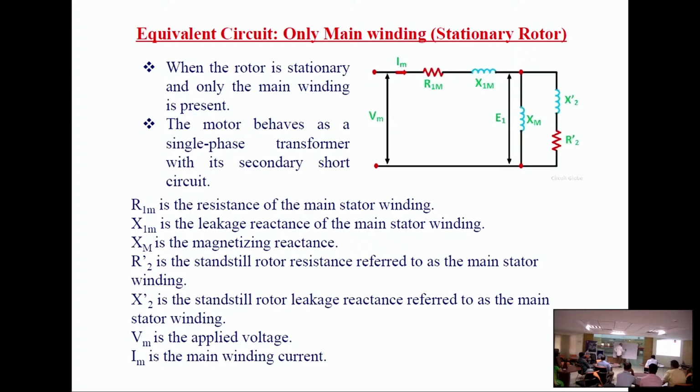Now this EMF has the supply frequency. This is E2 and R2 will now be R2 by S, and this is simply X2.